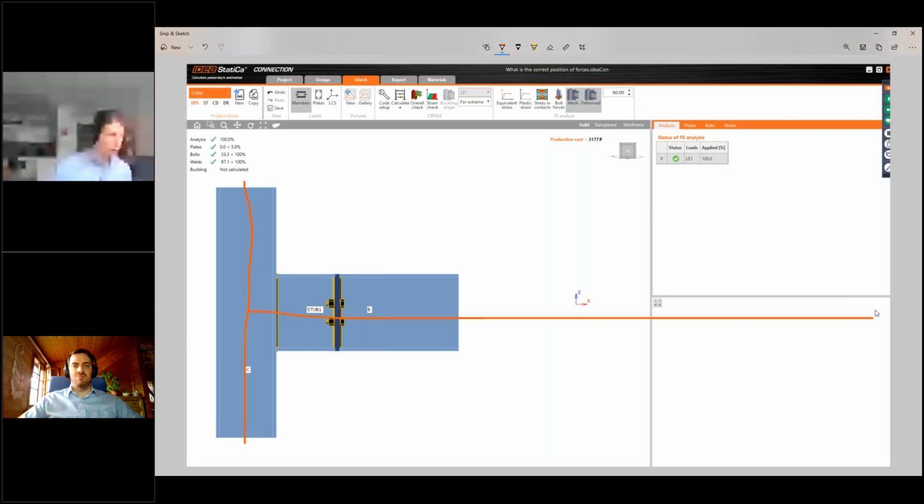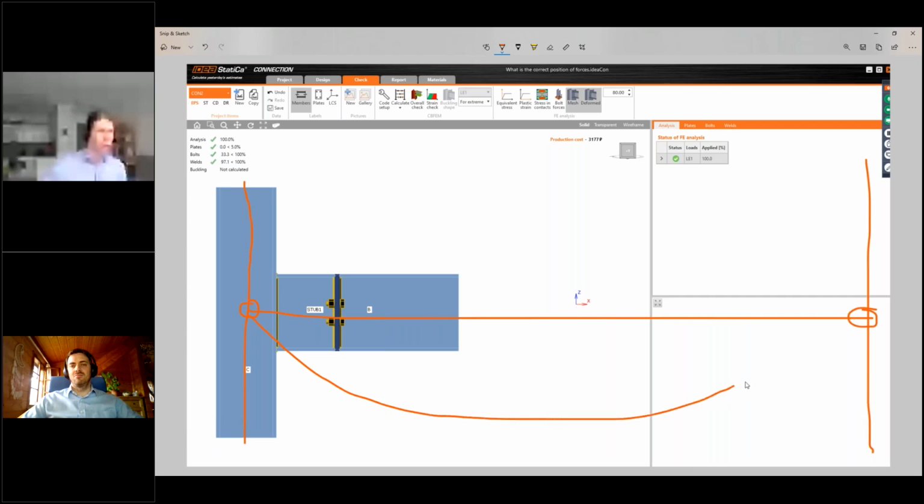Imagine the structure model. Just ignore my imperfect drawing. Imagine this is one column and a beam connected to another column, right? And I assume this is a hinged connection. So in SAP 2000, I would say there are hinges, and then the moment distribution would look like something like this, right? This is my moment. I can say it's minus moment, right?